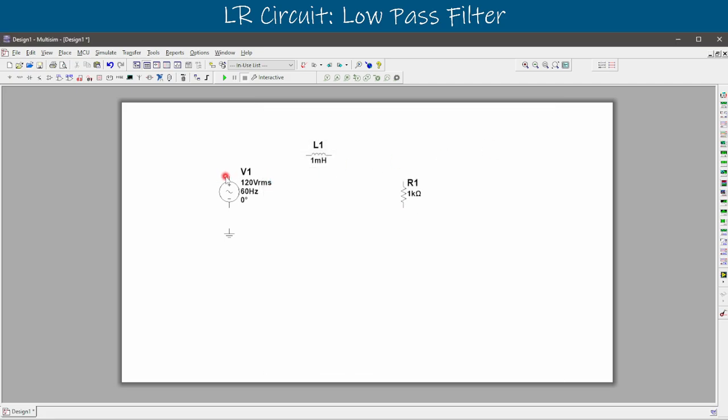Place that in because we can always change the value of it. Let's exit that. So from here, we want to connect these up in series. We'll place the voltage line into our inductor into our resistor, and our resistor leading all the way back to our negative terminal and ground. And so now that is our series RL circuit, and we do expect the current to flow up through this inductor and then down through this resistor and then back around.